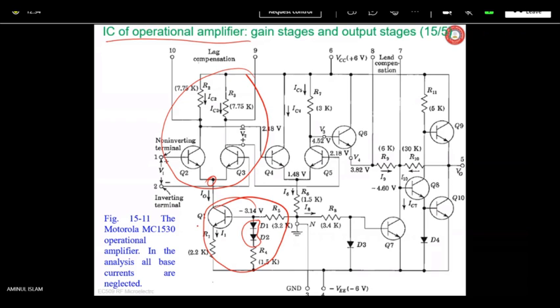isn't it? Aman? Yes, sir. So parallel combination, that is RL2 and RL3 is parallel combination of R2 parallel this 5.2 kilo ohm. So it is 7.5 kilo ohm parallel 5.2 kilo ohm gives you 3.12 kilo ohm. Okay, that is what actually effective resistance there.